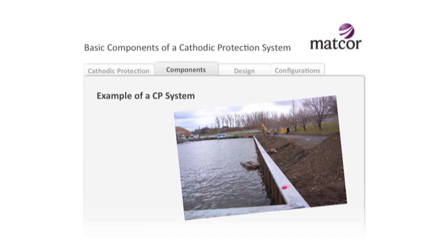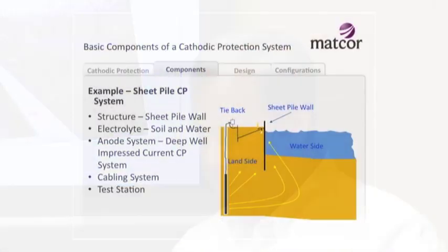And if you can see it closely, you can see there's a little bit of rust on the atmospheric side of the seawall. Okay? Rust is an interesting thing because for certain steel structures, rust becomes a coating, and it kind of slows down the corrosion after that. Okay? You could also paint that. But the bigger concern for this structure is what's happening in the soil side and what's happening where it's buried and in the water. We've got this seawall structure, okay?